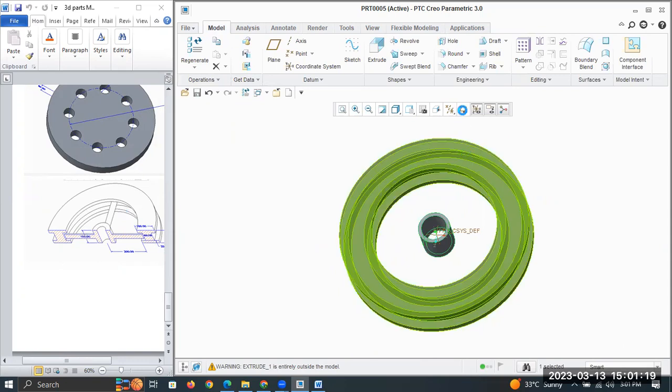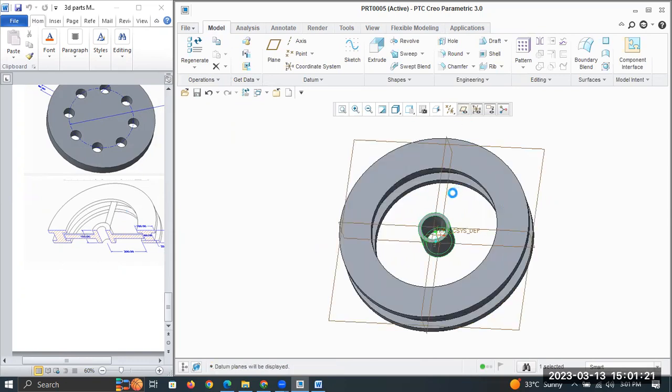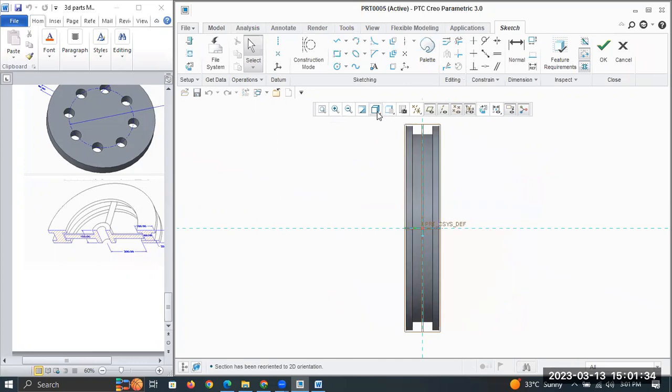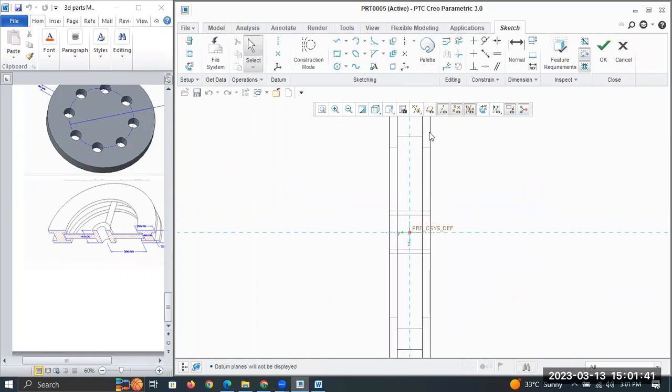So I am going to select the center plane again, but I'm going to turn on this planes display. This time I am going to select the center plane. Give a click on sketch view. Now this time this will be helpful if you want to see the back faces, then you can see this way. Is that clear? However, the hidden edges references I don't need now. That's why I have shifted that back to solid model.